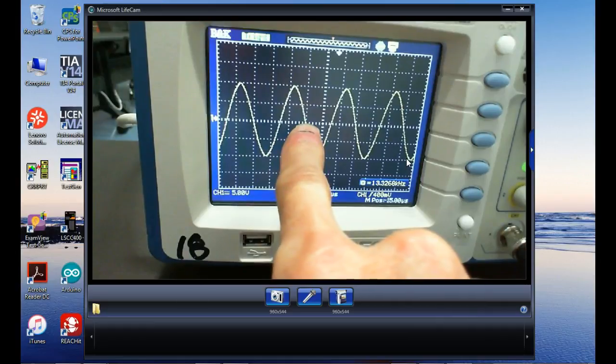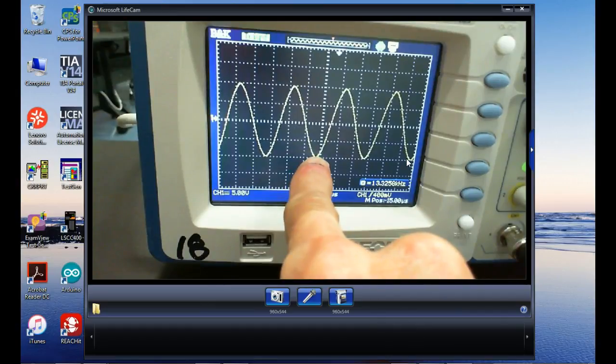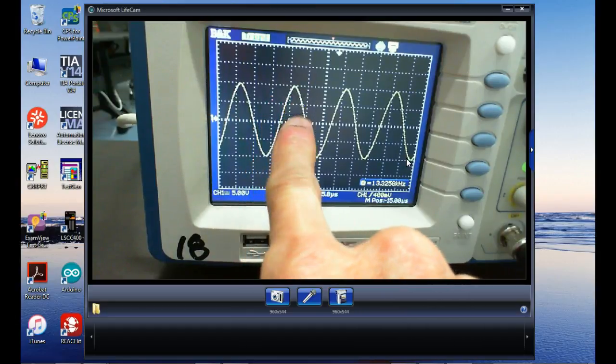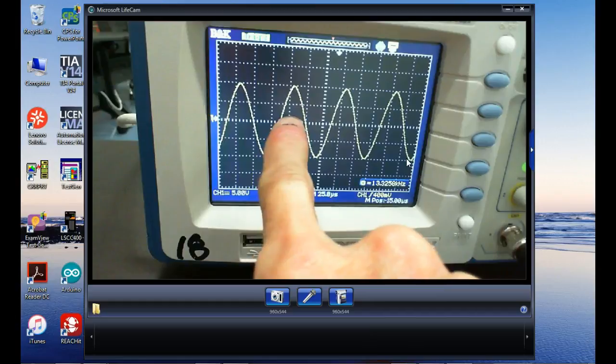The sine of 180 degrees is 0, so 0 times 10 volts gives you 0. The sine of 270 degrees is -1, and multiplying by the 10 volt peak gives -10. So that's what we mean. Anywhere on this angle, I could take the angle and calculate what we call the instantaneous voltage.